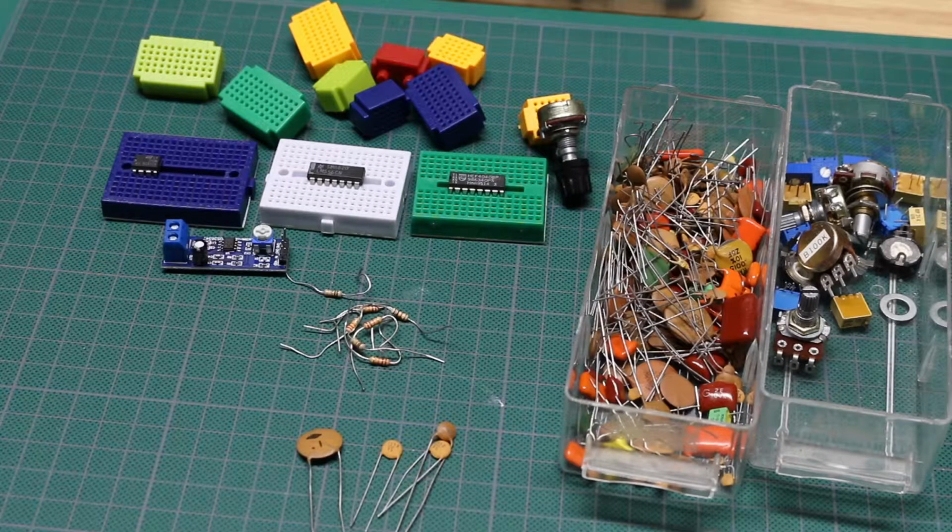Getting back to audio synth experiments, I'm going to try building the sub-octave generator that I simulated in LT-Spice recently. That's based on a 555 oscillator and then some flip-flops to divide the frequency by 2 each time it goes to another flip-flop in the chain. And every time the frequency is divided by 2, the tone produced is 1 octave down from the previous tone.